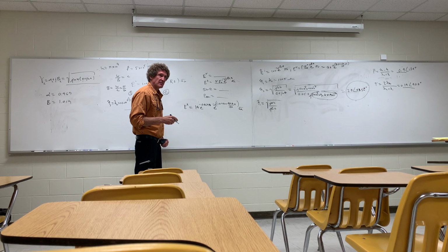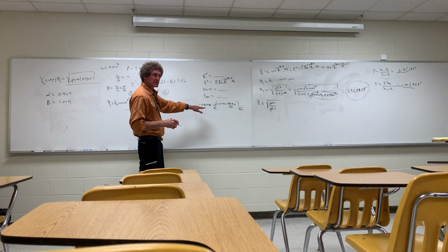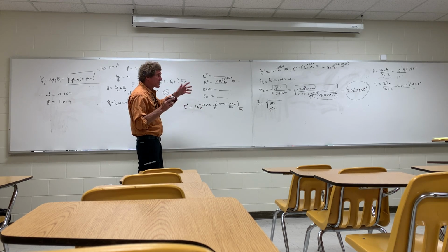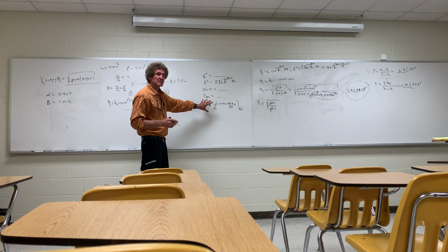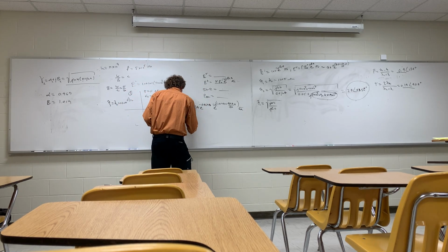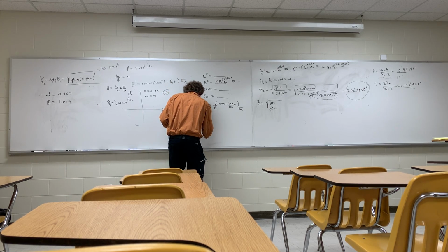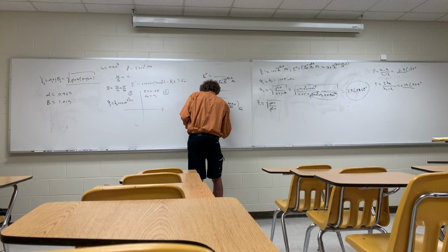Does he ask for the time domain form or the phasor domain? It doesn't specify, I think it's time domain. All right, how do I get time domain from this, by the way? Well, what we would technically have to do, we'd have to take this times e to the j omega t and take the real part. Really, I know all I'm gonna do is break out a cosine, correct, class? When I do that in the time domain, it's gonna become simply 14, you'll still have this e to the minus 0.969z, and then you're gonna have cosine of omega.